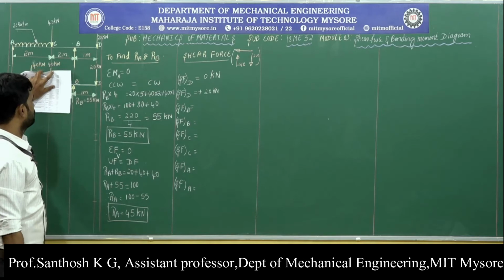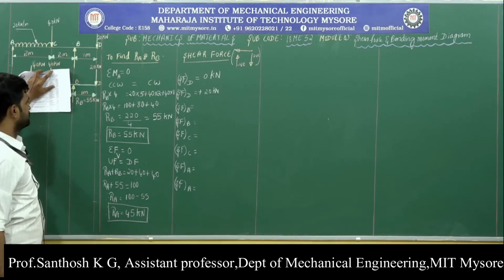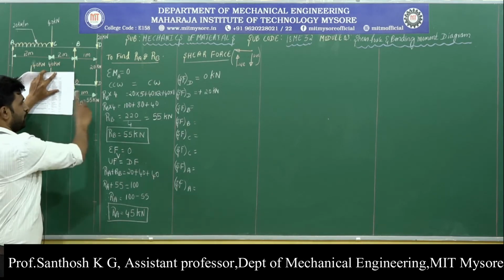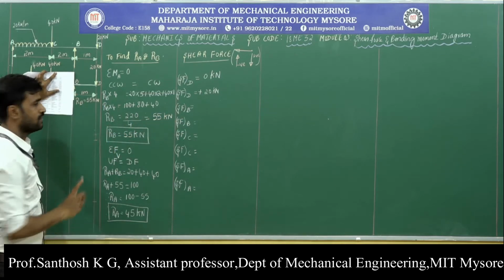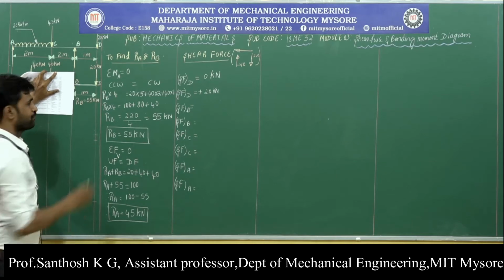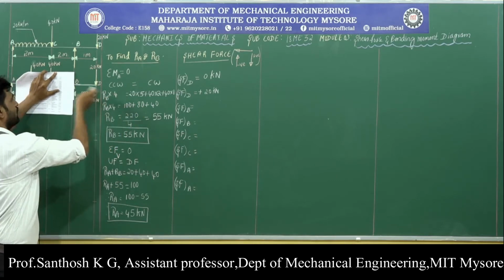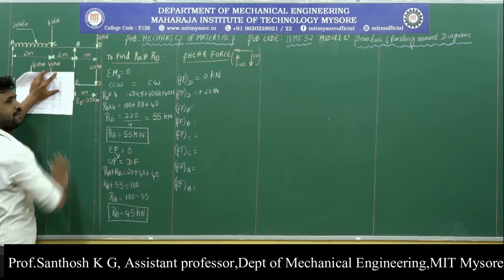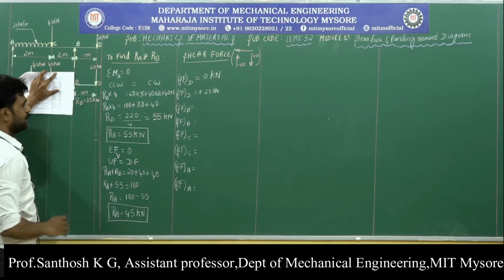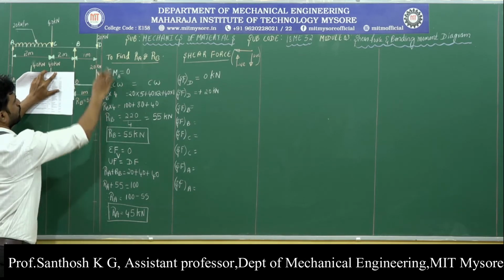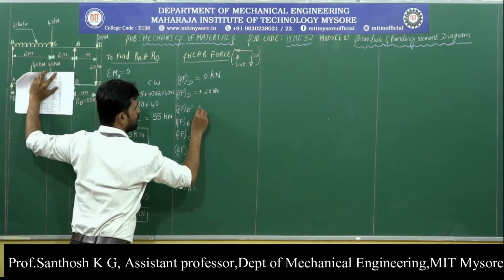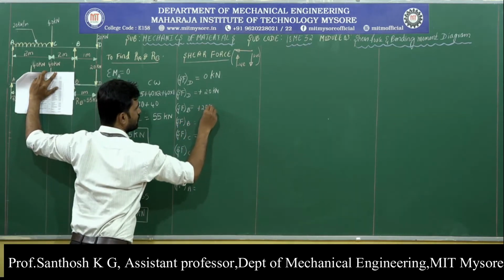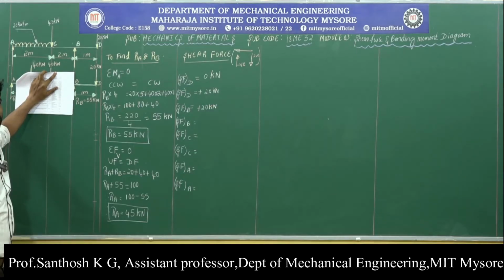Now, I will come to the next point, which is B, but while finding the first value of shear force at B, we should not consider the shear force acting at B. Now, when we move from right side up to point B, we find only one shear force at D, which is having a magnitude of plus 20 kilonewton, because it is acting in downward direction.